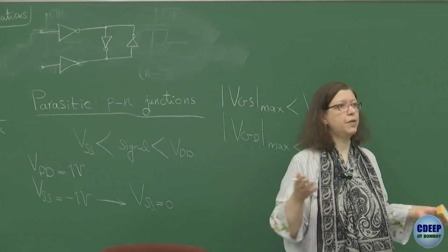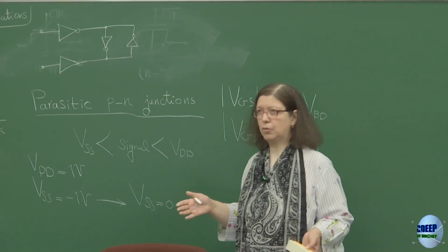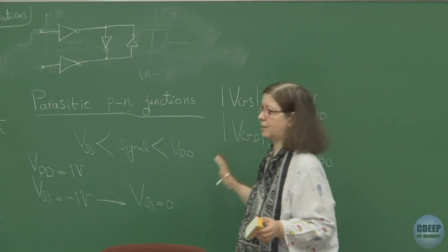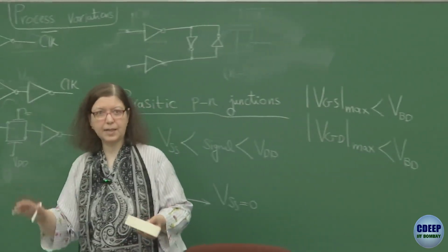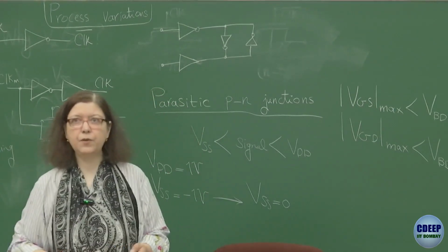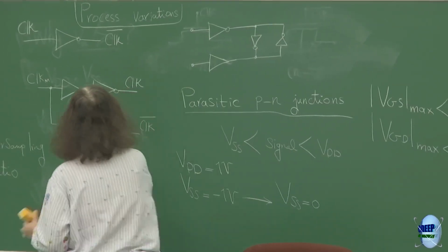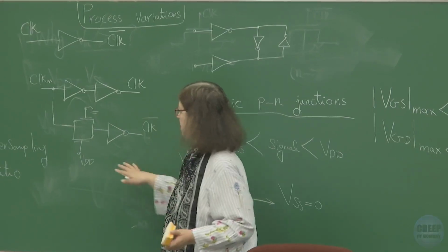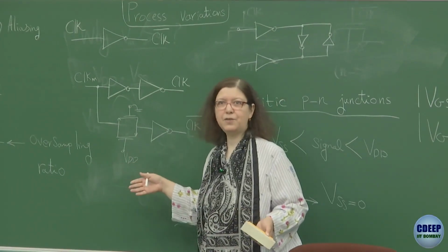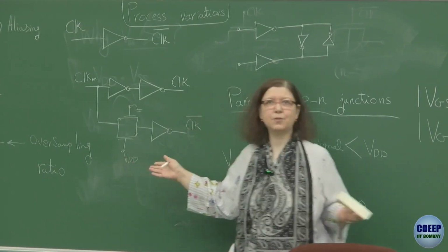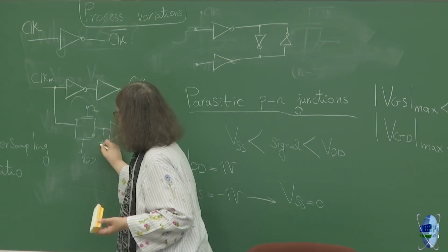But this is for your information only, because in this course we are not really looking at clock generation and clock recovery techniques. That's again a separate topic. But just for your information, yes. This one: this is a switch which is always closed, but it has its own delay, because we know that there is a time constant associated with that. There is a parasitic cap at the input of the inverter.